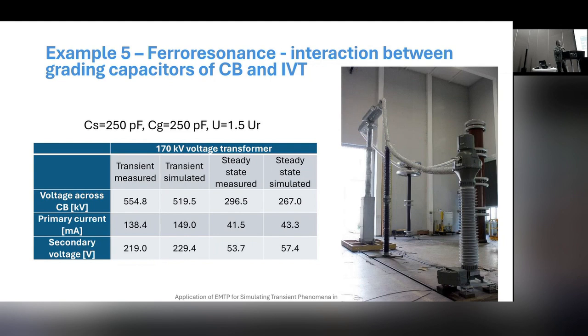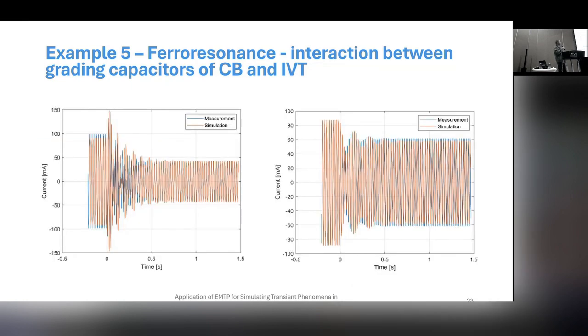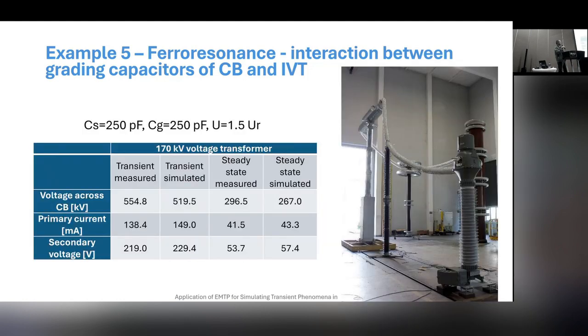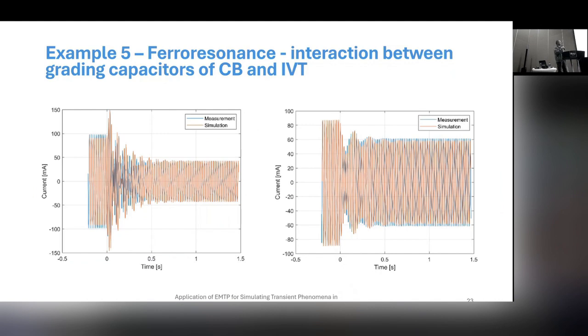So in this case, as you can see here, there was no ferro resonance. I will show some waveforms on the next slide. For example, we have the current through the inductive voltage transformer, to the primary winding, and after this connection you can see that we have a 50 Hertz signal. Basically, we have a capacitor divider, which means that some voltage will be present here due to the capacitor divider, and we basically don't get any ferro resonance. Similar for this case, okay.